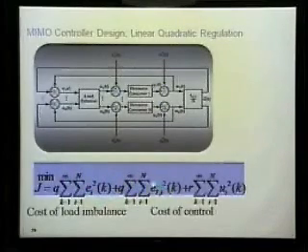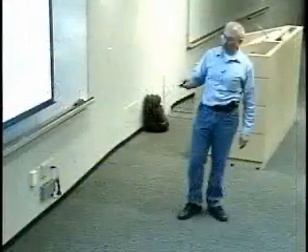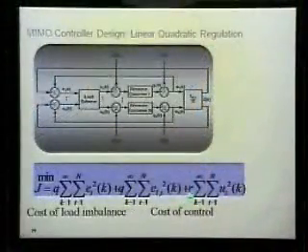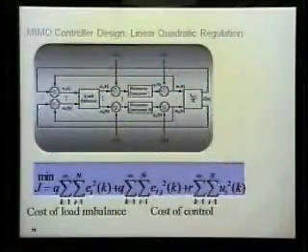These E's here are two aspects of the control error. One is the cumulative error, and this is the instantaneous error. And what we did is we figured out the control design is about figuring out a weighting factor Q that's used here to indicate the accuracy versus the weighting factor R over here, which is about the control frequency. So the more control you do, the more you're going to hit throughput because you're thrashing things around. And how much does that buy you relative to the accuracy of the control here, which is going to minimize your throughput? So that was the way we handled that one.